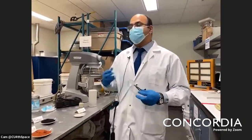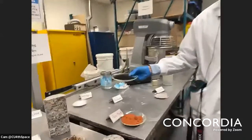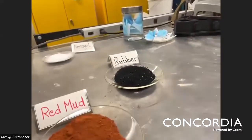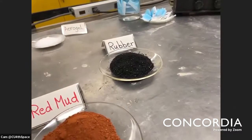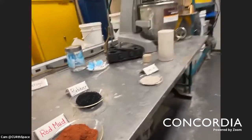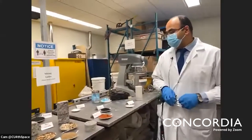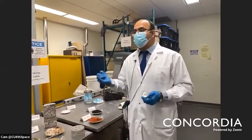Okay, sometimes we need to make some treatment for it. For example, this rubber, you can use it directly, but it's not going to give you that performance if you don't start by pre-treating it with sodium hydroxide. It will increase the bond and will give you higher performance. Okay, so that's the main point, that you have to think about the application first.